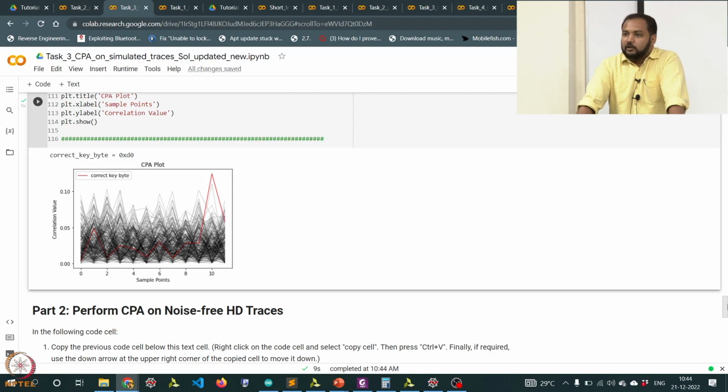Using a real probe, when you are collecting traces using an EM probe, you ideally need at least 4000 traces, even with the least amount of noise. So this is the basic of the CPA attack. We can stop here.